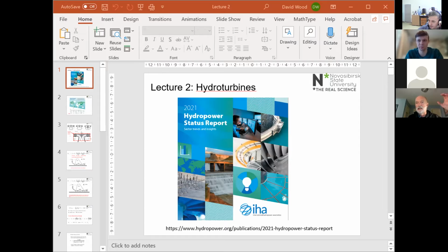Okay, you're just interested in what's coming in and what's coming out. To do a thorough design of the turbine, to choose the number of blades, even if they're circular arc blades, you still have to choose their length and you have to choose their orientation. And the only way that you can do that in detail is computational fluid dynamics.